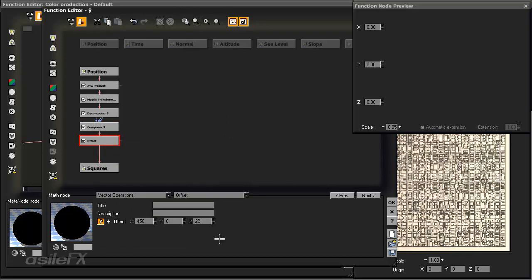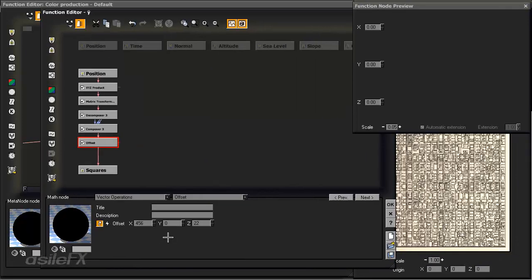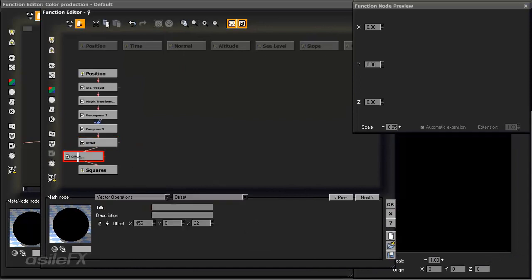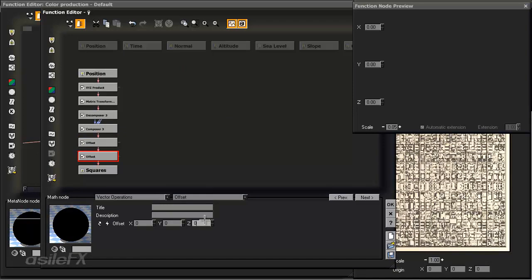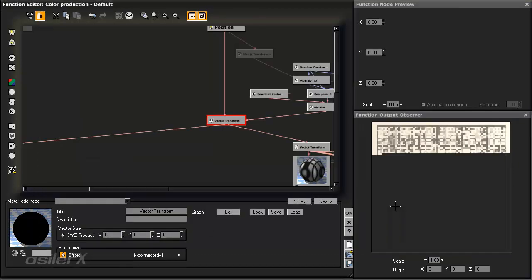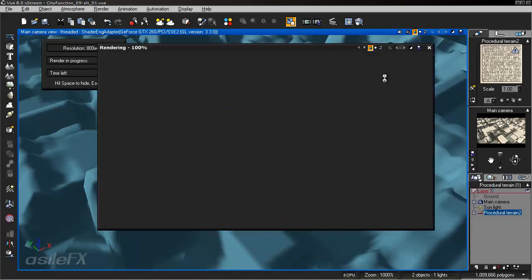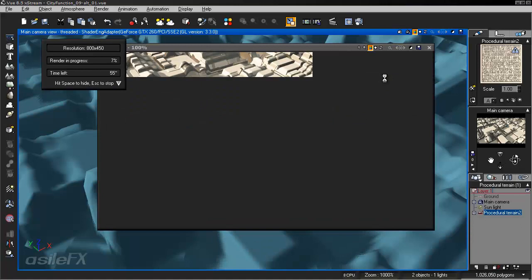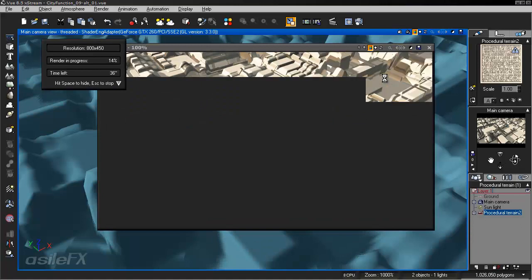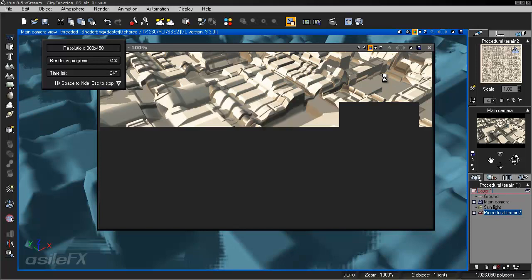and right now that is being published because I have it connected to that on-off switch, which is currently off. But I'm going to add another offset node, setting it 0, 0, all the way across, except on the Z, where I'm going to enter a negative 5, just a very small amount of offset. So it should keep things really close, but we'll start to add extra little details around the edges, just with a little tiny shift. And that way we can pull out even more of the look.